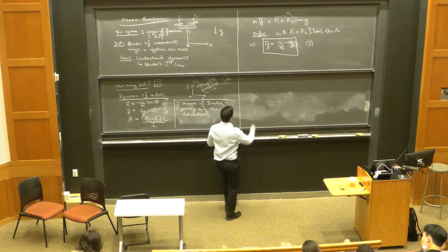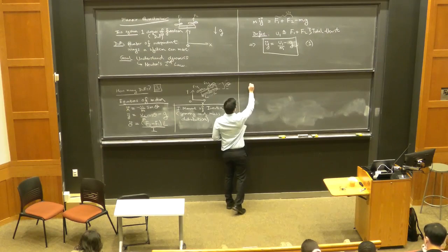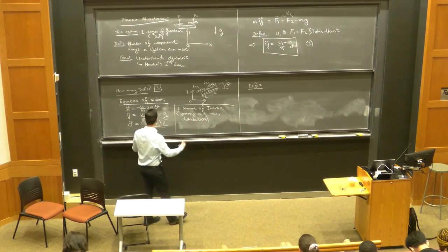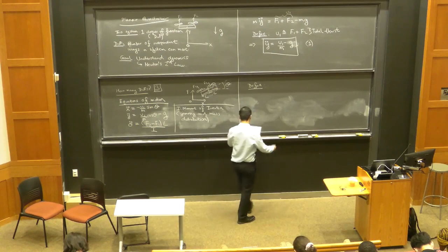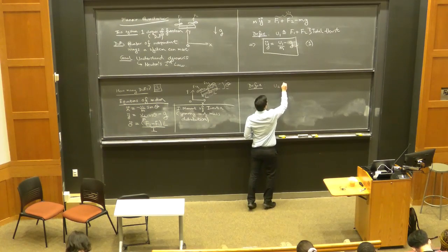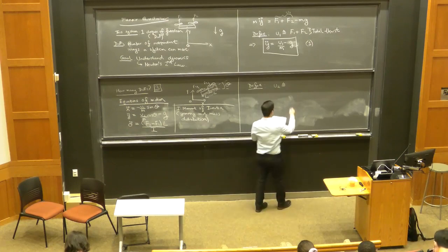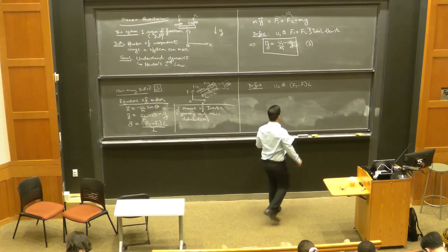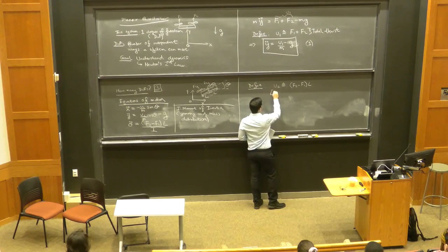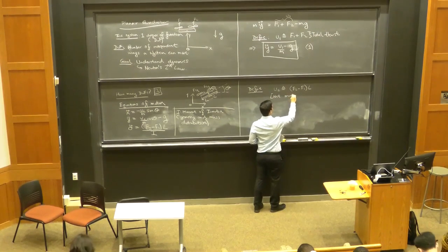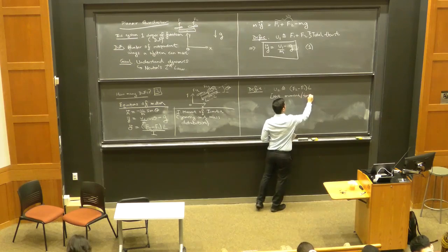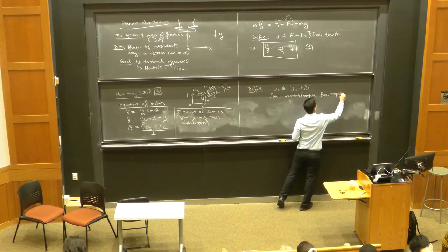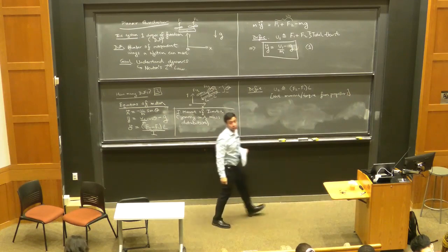Okay, I'm going to just define one more quantity here, just to make the equations a bit more compact, and again because we're going to use this notation later on. So I'm going to define U2. I already defined U1 up there. I'm going to define U2 as F2 minus F1 multiplied by L. So this is the net moment or torque from the propellers, from our two thrust forces.